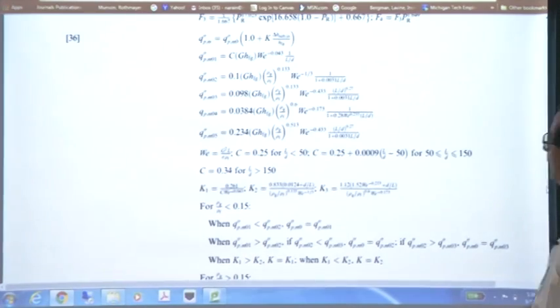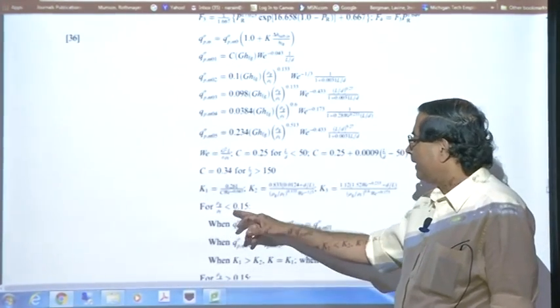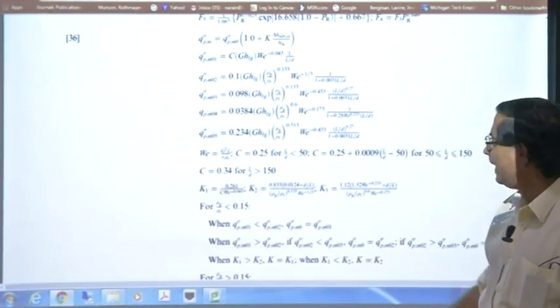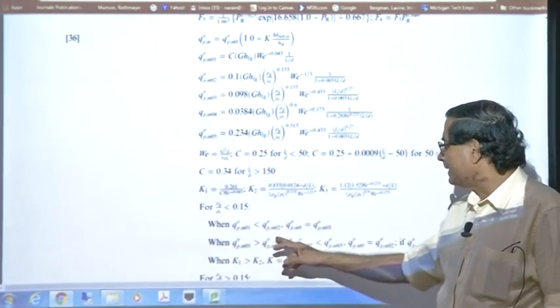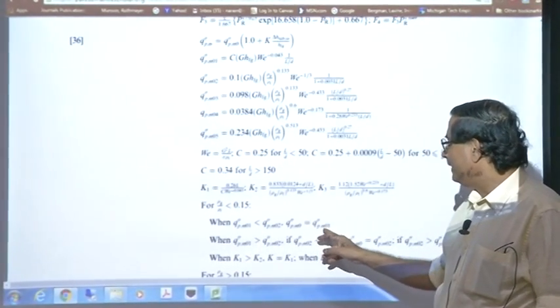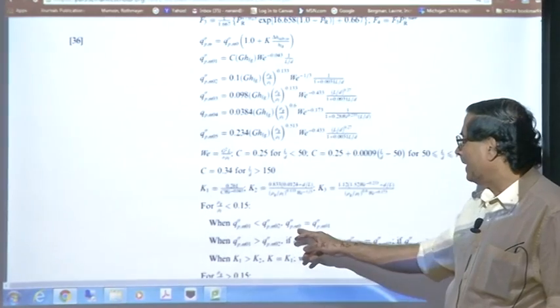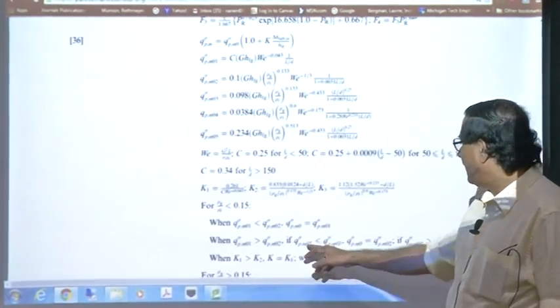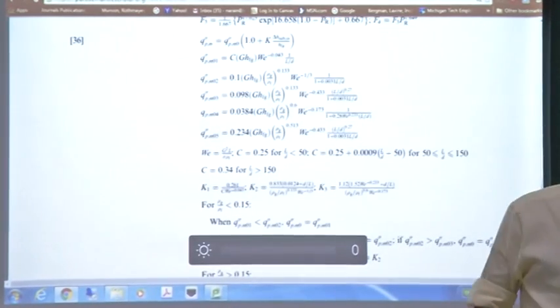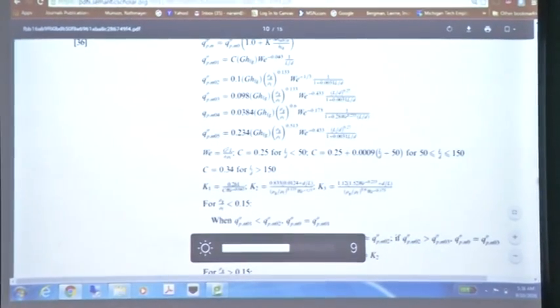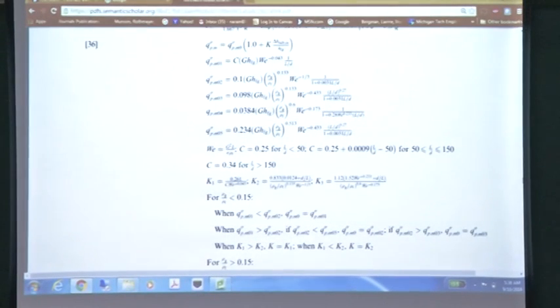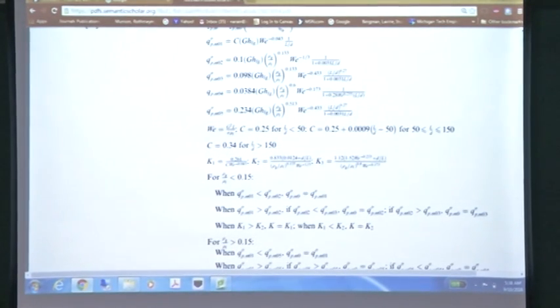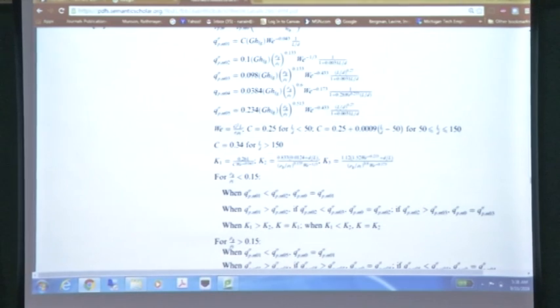Then you go through: is your vapor to liquid density ratio less than 0.51? Is this number less than that number? If that is so, then this q double prime PMO is equal to PMO1. Then if it is the other way around, and so certain logical constraints, you can set it up. And the reason it looks a little weird like this is because it's probably trying to cover 2-3 different mechanisms of CHF, and not all of them.